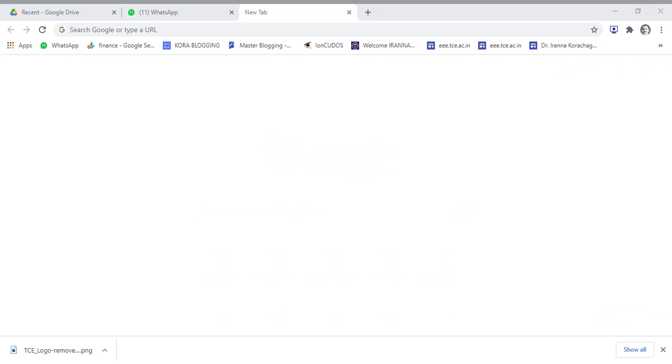So if the temperature is more, we may feel the heat when we are holding the handle of the iron box, and there must be a permissible heat. If it is too hot, we may not be able to use the iron box. In the similar way, for the circuit breaker also, we test the temperature rise of each part of the circuit breaker, whether it is within the permissible, stated, desired value.